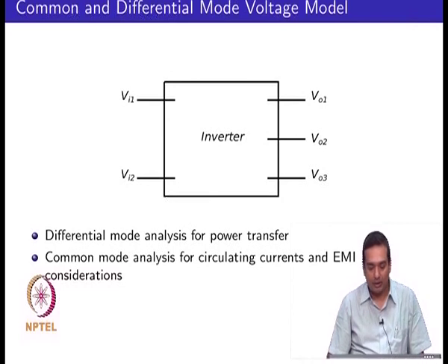So, the study of the differential mode operation of it is an important part. The common mode signals are important when you are looking at other perspectives such as the possibility for circulating currents in the converter, and the EMI characteristics, the EMI perspective of the power converter.